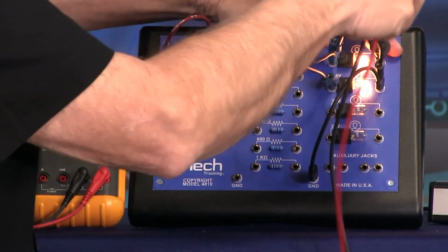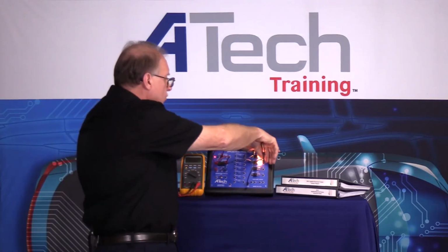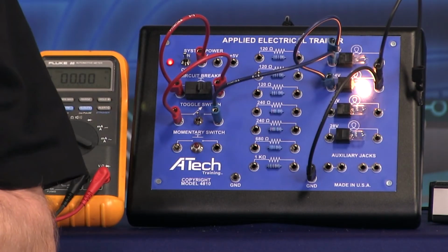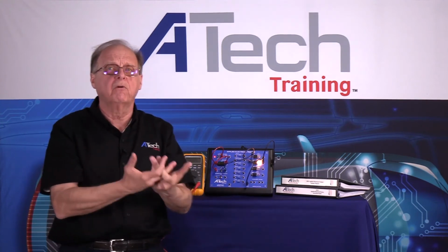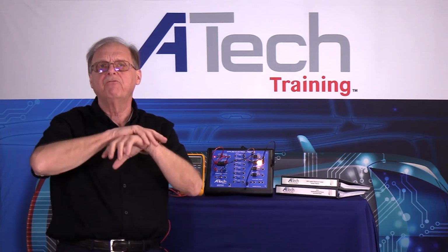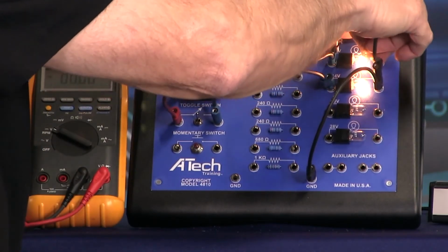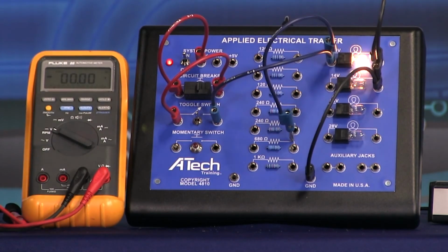The neat thing I will look at on a parallel circuit, if I remove voltage to one side, so I'm going to remove what on this one? Ground. The only circuit having a problem would be the one it's on, and the other circuit is okay. So if I'm feeding voltage to both circuits on a parallel circuit, one light bulb can go out. If I have a bad bulb on a series circuit, that means the whole circuit goes out, so it's a little bit different. If I come back over here, that is on the ground. Let's say I lose power to this side. The other side still works. So we have ability to look at the parallel circuits going across, all right?